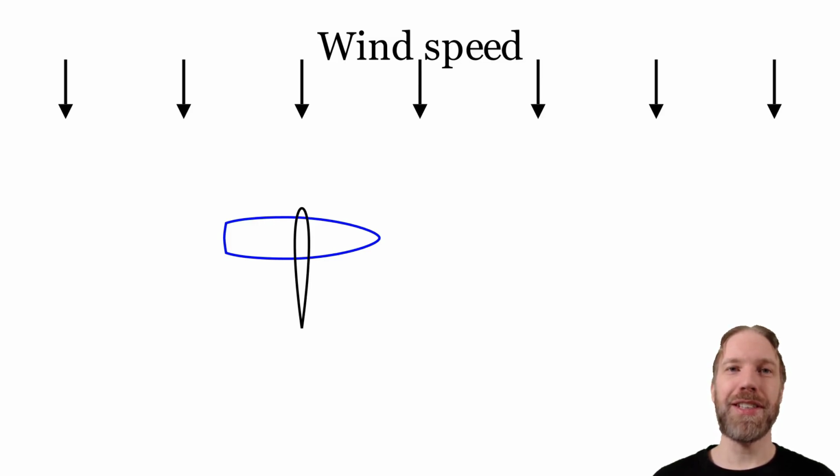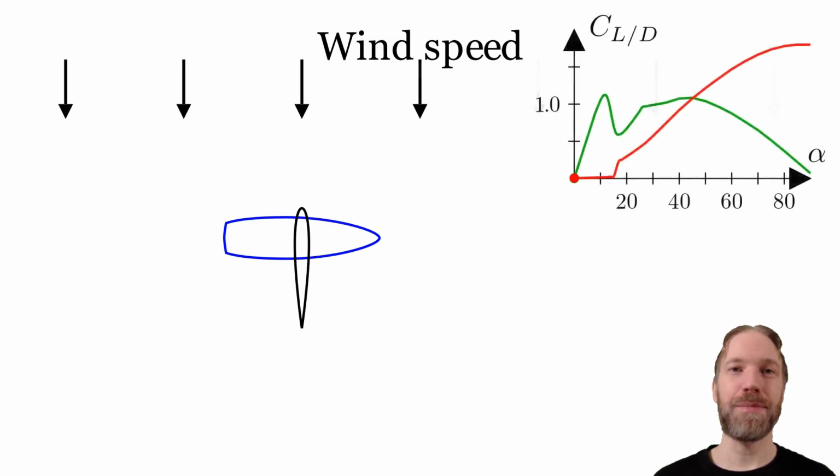The lift and drag coefficients of this airfoil can be seen in the figure. The green line is the lift coefficient and the red line is the drag coefficient. Alpha is the angle of attack, which at the moment is 0 for this blade. The initial peak for lift is at 12 degrees angle of attack, and drag force starts to increase significantly at about 15 degrees. This is what we call stall, which decreases the blade performance. The data we see in the figure is measurement data for the NACA 0012 airfoil, which is the airfoil that is drawn in the figure.